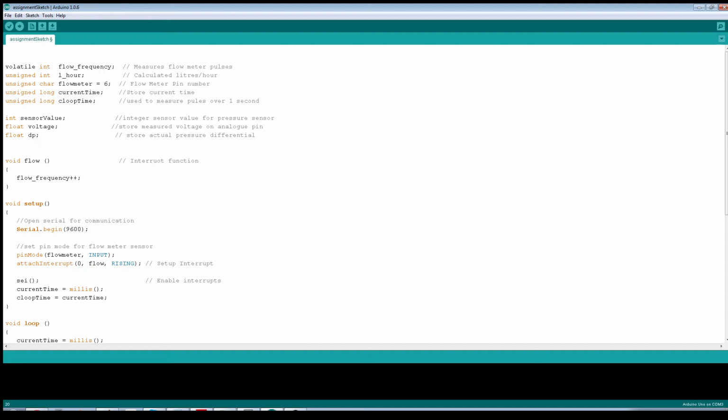So if we make a plot of flow rate versus system head, then we'll find out how well our pump performs over a series of different environments. If we were to design a specific pipe network, we'd be able to determine the system head based off fluid dynamics theory, and then you use a pump performance curve to test whether or not our pump is going to be sufficient.